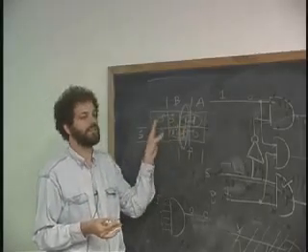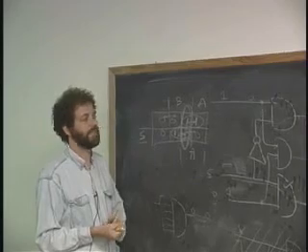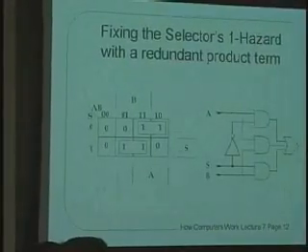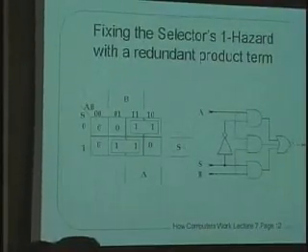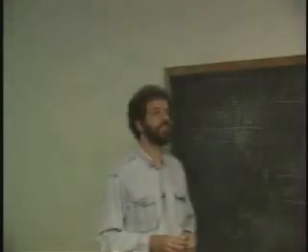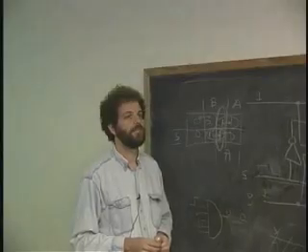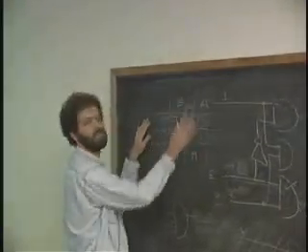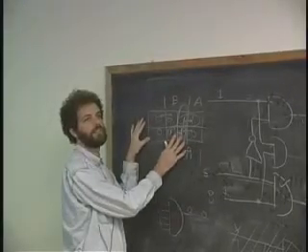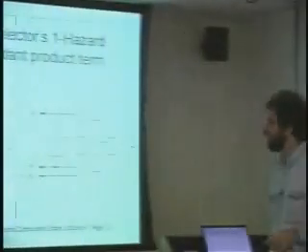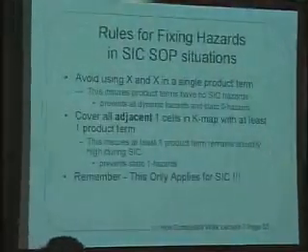But these 1 to 1 and 0 to 0 hazards do make a difference, and I want to explain how they work. So if you switch the switch, this is hazard-free. If you leave it on B, or B determines, you switch B from a 0 to a 1. It's actually hazard-free for everything. That's also hazard-free as long as it's a 1 input. If only one of them changes, I don't need to know what these 3 things are to tell you that this is a hazard-free circuit. And pacemakers are built to be hazard-free? Oh yeah, for sure.